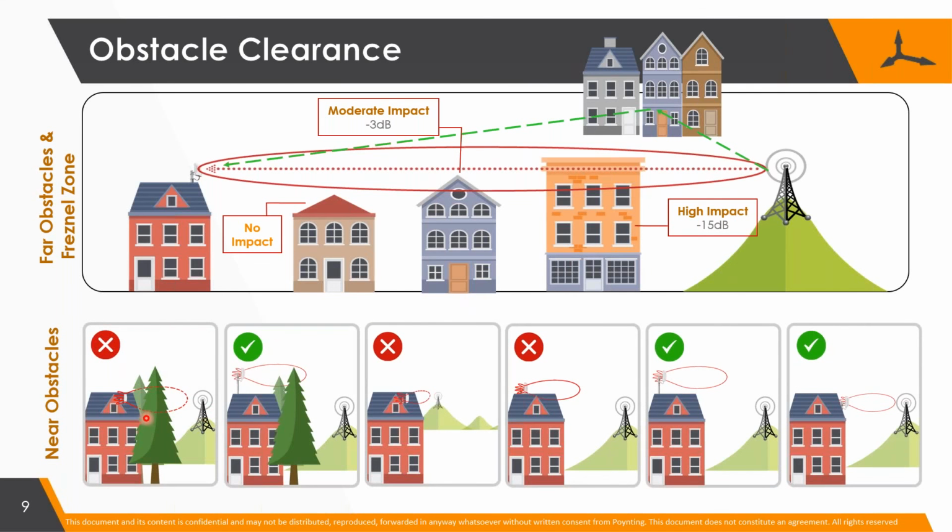Here's a little scenario. Here you've got, say, very close trees, and you can see on this side, it's often quite useful just to go further away from these trees. Of course, going up is also useful, but just moving further away from them gives the wave time to expand and get through, like I say, the gaps and so forth in the tree. So as counterintuitive as it may seem, it's quite good to sometimes move back, and it's typically always good to move higher. Here's another instance where part of the house could actually be cutting off the beam of this antenna.